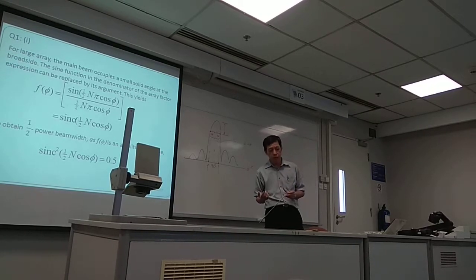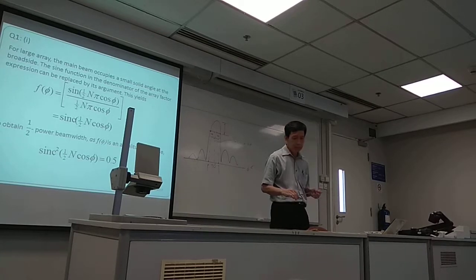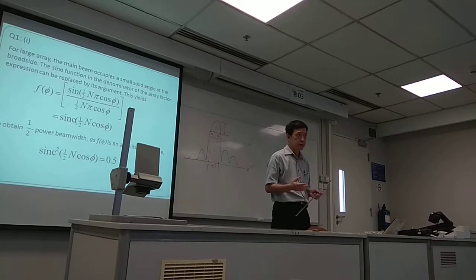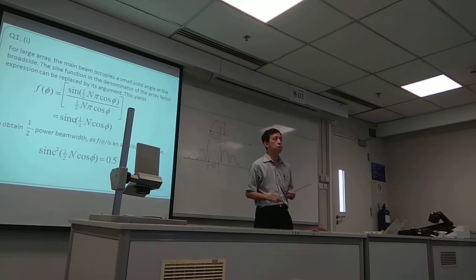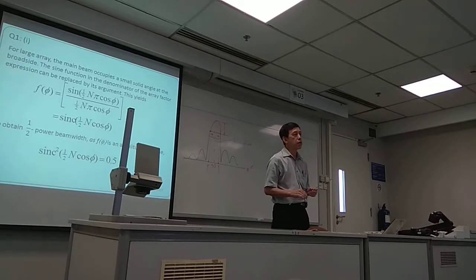And in fact, it is actually not necessarily an array of inter-element spacing of half wavelength. In fact, there is no such requirement. In many applications, we can afford to violate the so-called spatial Nyquist sampling theorem.